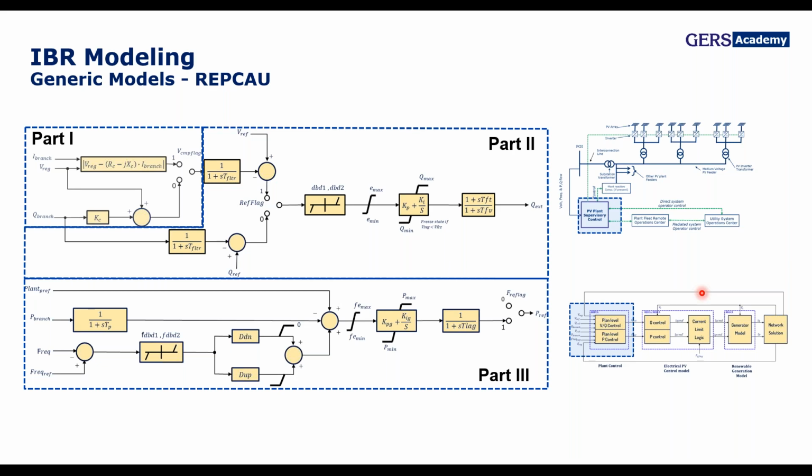So these are the controls that appear on a PPC. The model in the figure represents a different portion of that PPC controller. Yes, the first one allows droop compensation through the current that flows to the interconnection line, and uses the voltage and current signals. It goes through a filter and after that through a deadband, and finally injects into the system.